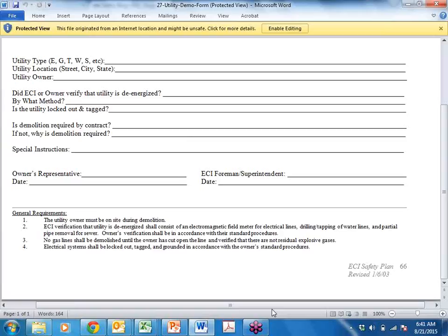George? I've always tried to mark it as you're backfilling it, so if you ever have to go back, you have something to witness. Mark it, maybe put some ties on it, and throw it in the log field book. If it's electric, I want the owner to go. We will be taking some electric out at CCTA, so it's a good refresher when we actually take that one out.